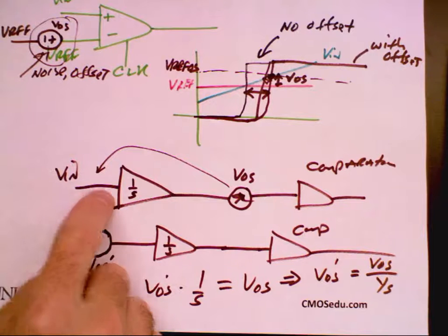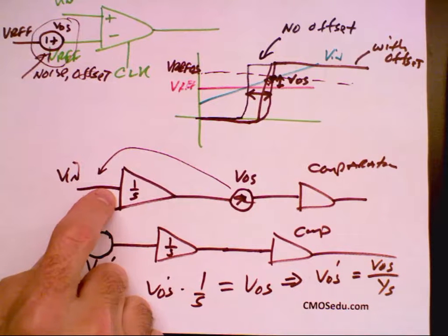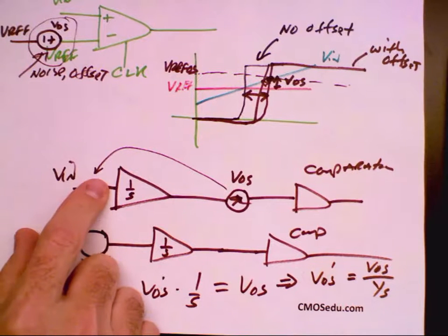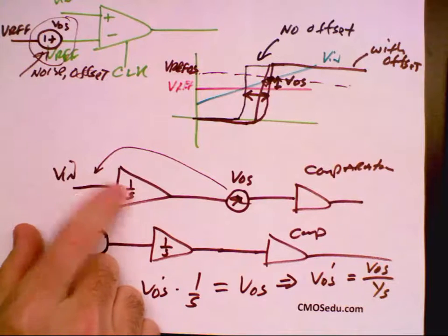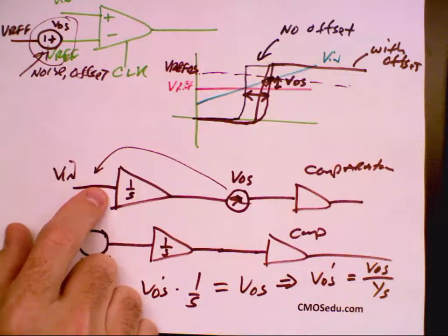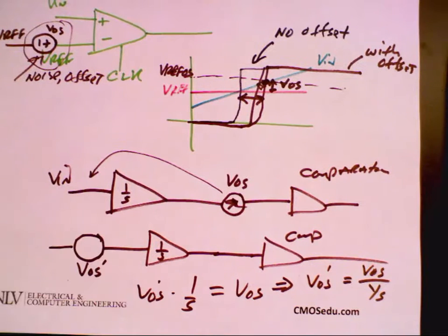What happens if I have offset noise here with the op amp? It's not going to refer back by dividing by some high gain, right? So it's going to add directly to my input signal. So if I have an offset in my op amp, it's going to shift the output signal by the offset, because it adds directly to the input. I don't believe you. Prove it.